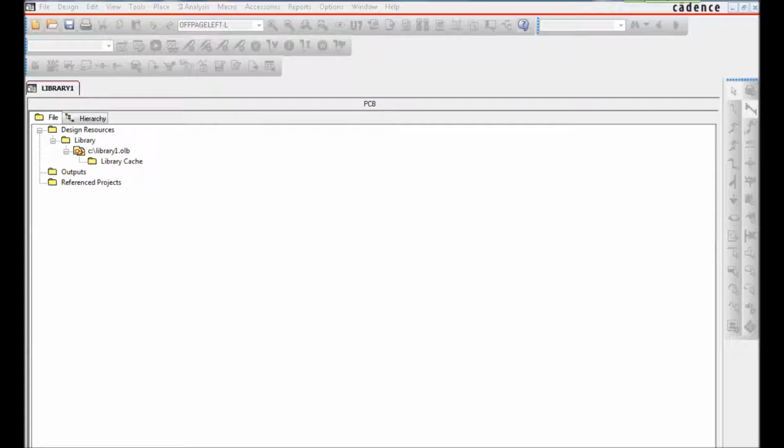One important thing to mention, though, before I let you guys go: when you create a new library, its location defaults to a directory within the Cadence software hierarchy. Also, the capture libraries supplied by Cadence are organized by part function, such as op-amp, discrete, gate, etc. It is strongly recommended that you organize your new libraries in a similar fashion. You can also rename your library at any time. You can modify the name and or location of a library by clicking on the library with the right mouse button and then selecting Save As.